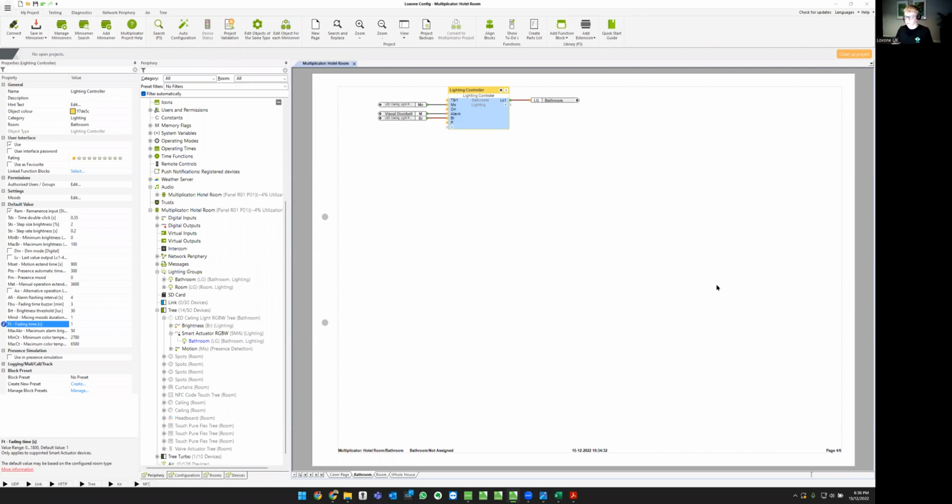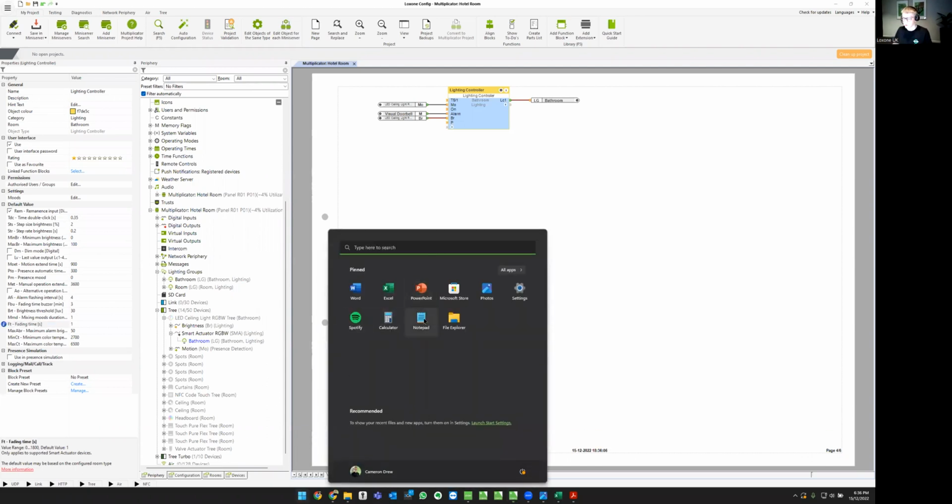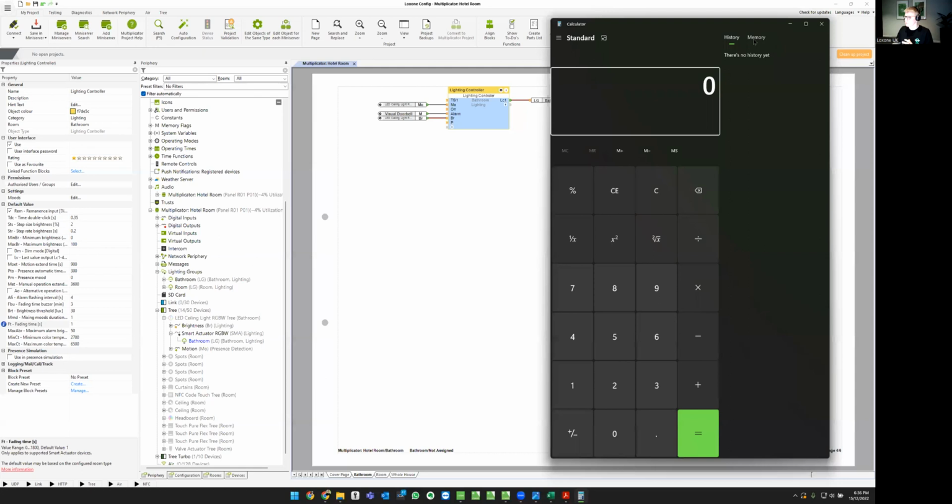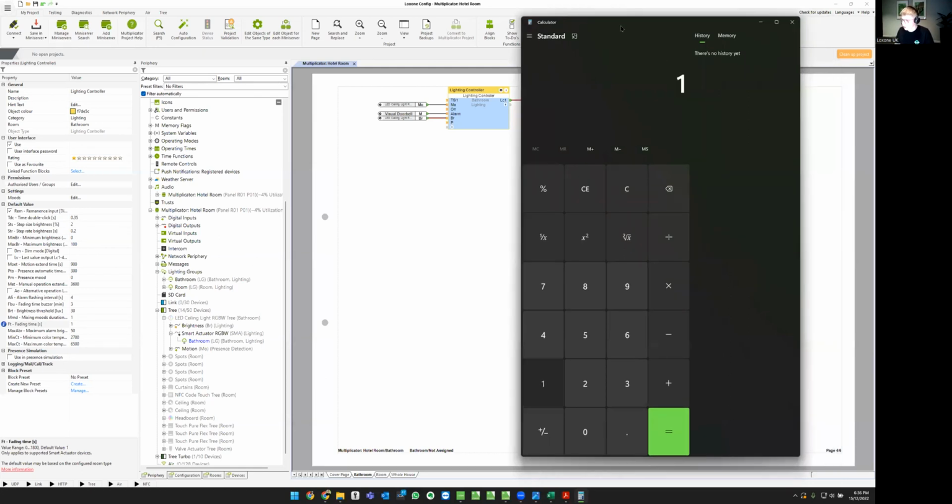So let's say for our example that your conventional solution, when I say solution, I'm talking about audio solution, is 100-watt channels for audio. Now, this is a standard AB amplifier, and you will find that even if the speakers aren't driven at 100% power, which in nearly any restaurant or hospitality venue you go to, they won't be at 100% volume, it's still using 100% of the power.